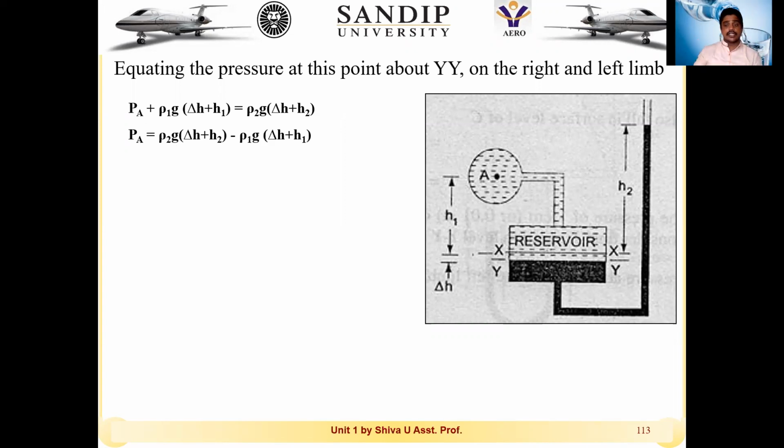So in the case of the reservoir, what is the need of the reservoir? Why can't we go to the general constructions as in the previous one? Here our interest is to know even the finite variations of the pressure, that is, the minute variations of the pressure. In order to improve the accuracy level, the reservoirs can be adopted. But the reservoir area should be 100 times the actual tube area, that is the right limb area.